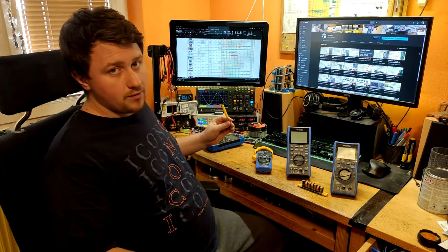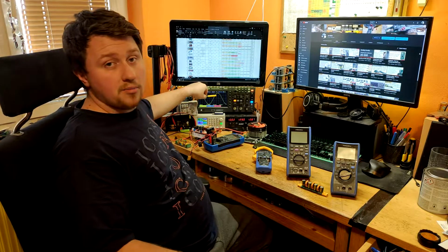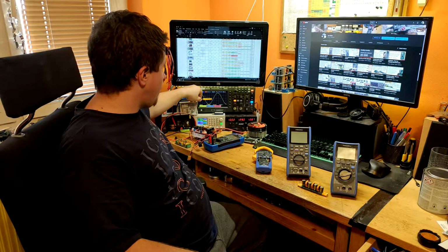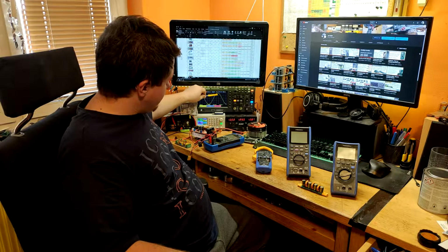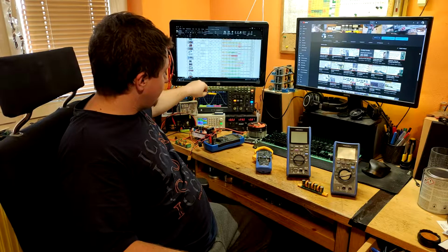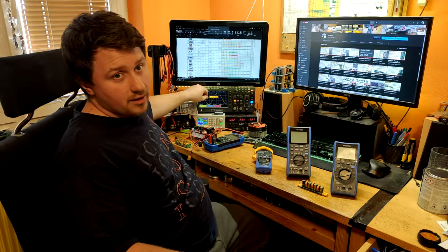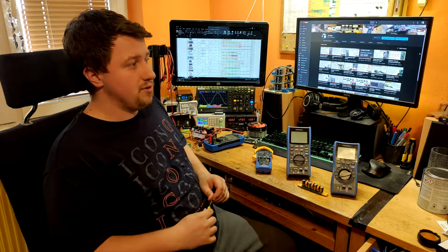If you have enough of these supplies, they actually can make the voltage uglier, because if they only take huge current spikes in these areas and in these areas, then they tend to flatten the voltage, because they only load it in these areas, so the voltage always goes down. It's like if you put something under heavy load, its voltage drops. You know that when you are starting a car, for example. The distortion will actually come closer to square, so that's why we were referring to square wave so much.